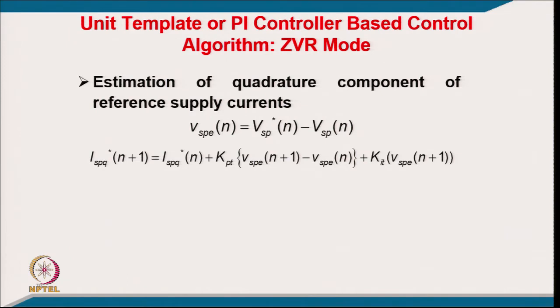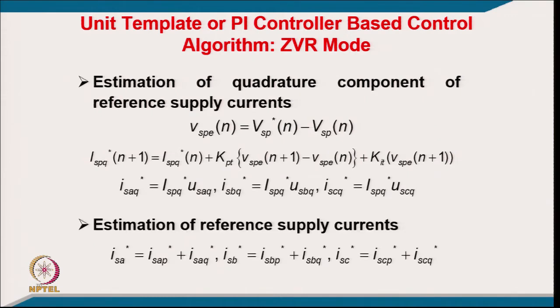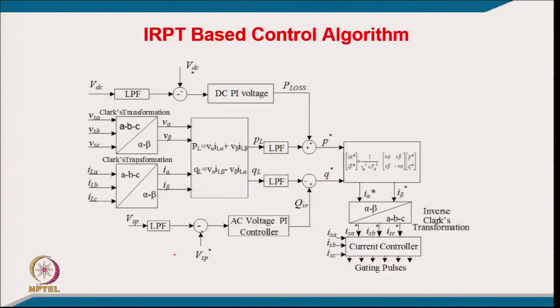This we consider the amplitude of quadrature current which is at 90 degrees leading the phase voltage, and then these are the instantaneous values of them, and summing both the phase component and the quadrature component we get the 3-phase grid current, and taking the sensed grid current we put the indirect current control for the shunt active power filter.